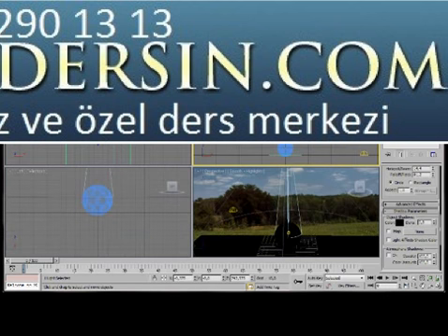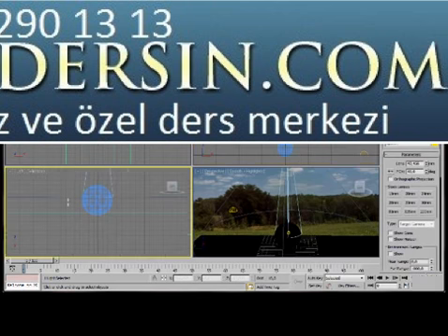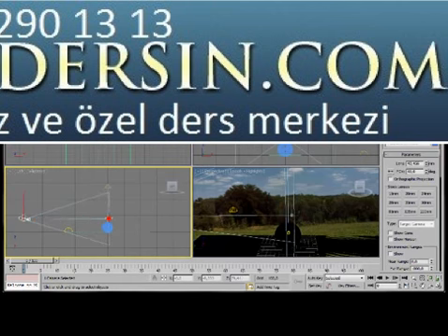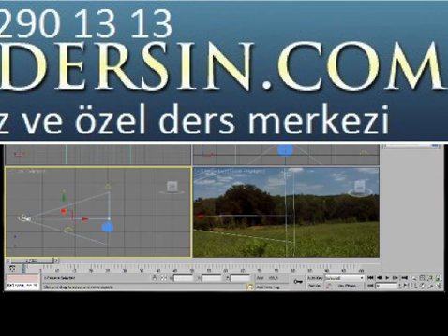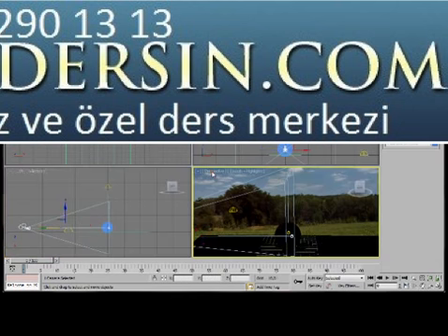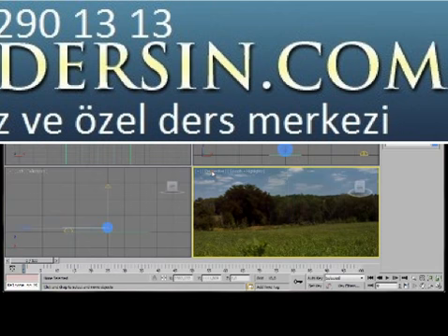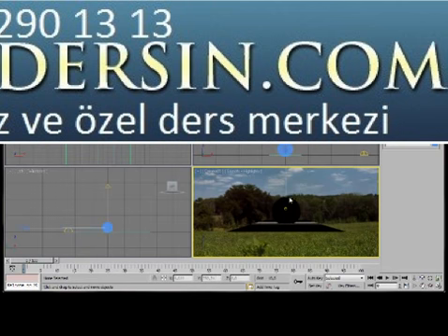All we need to do now is add a camera. Let's go back over to the panel, choose cameras and a target camera. In the left viewport, let's set our camera. There we are. Back in the perspective viewport, click on the word perspective, then cameras. Let's correct the position of our plane.